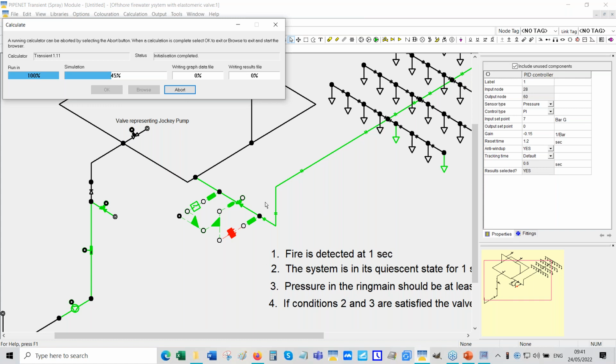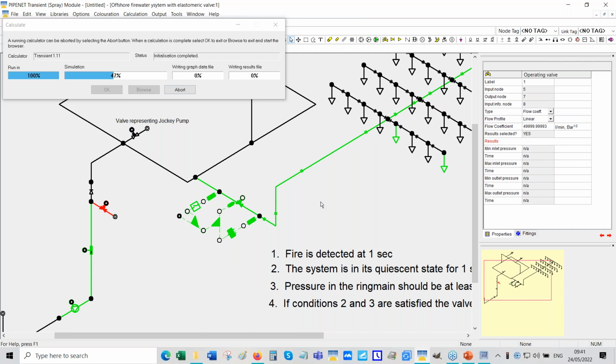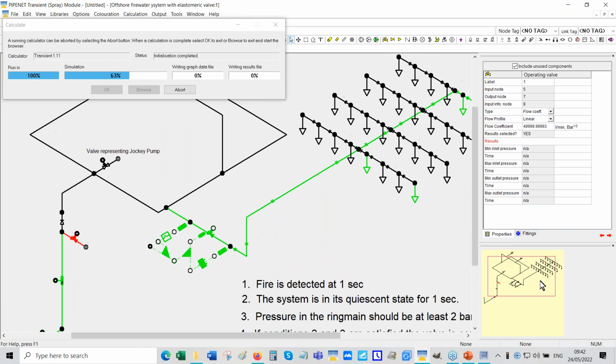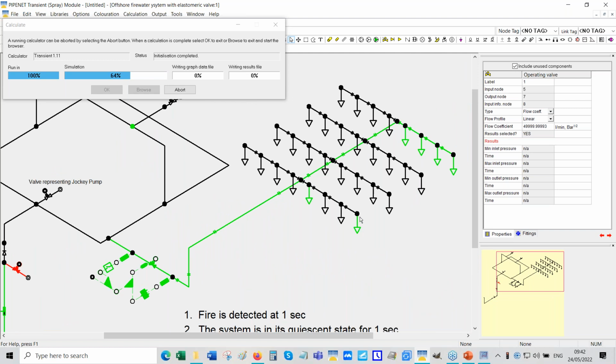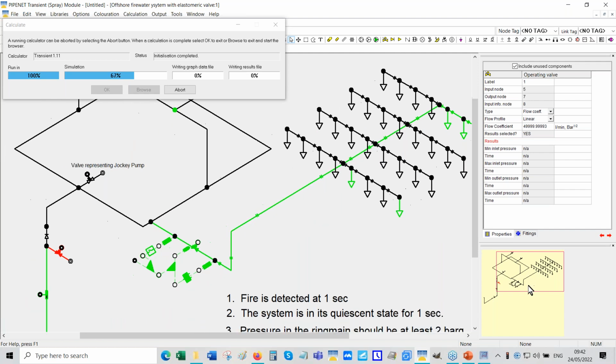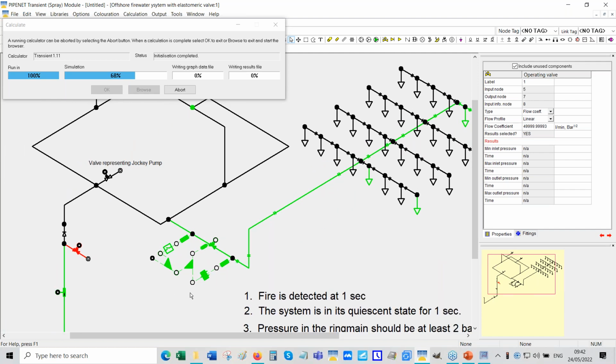It's actually quite a complex model. First of all, you've got this overboard dump valve that closes, and then we've got a dry deluge system which needs time to prime. It's a very complex calculation. The network looks simple, but you can imagine how difficult it is for PIPENET to see how the flow goes along the line and all these pipelines, and then how the nozzles discharge one by one, and all those things. On top of all that, we've got this control system here.